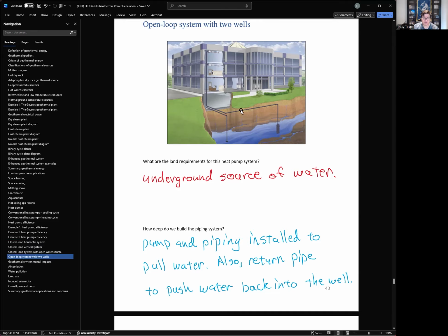You're going to physically draw that water into your building, and it's going to go through all your piping and cool your house down, and then it'll spit the warm water back into the well water, and it'll just cool back down. And you're just going to be constantly pumping water in, and it's the same idea. This water is going to be a constant 50 degrees Fahrenheit, and it will help stabilize the temperatures whenever it's really cold or really hot outside.